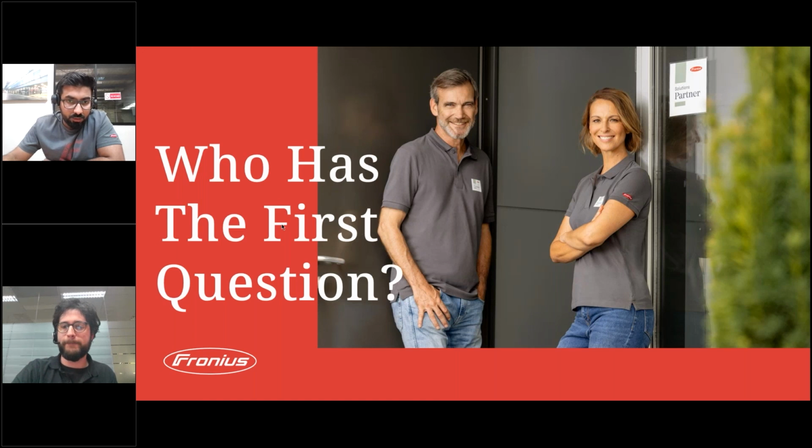Okay, there's a question from Gavin O'Donnell. It's not relevant to this topic, but I'll just try to answer it quickly. You get an error 20101 when you're trying to log into the SOS app. The first thing you need to make sure is you have an installer account, and your email is registered on SolarWeb. If that's done already, then I would recommend using another browser, or clearing the cache or the browsing data of your browser and trying again. If you have any questions, just feel free to send us an email, and we'll get in touch with you.